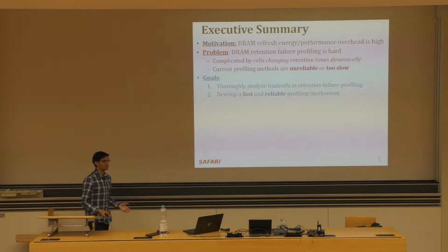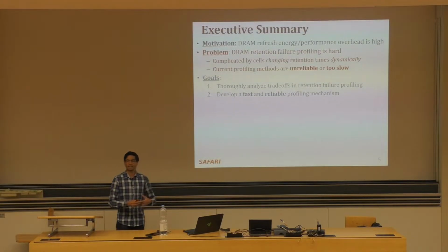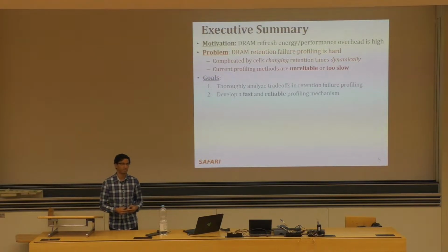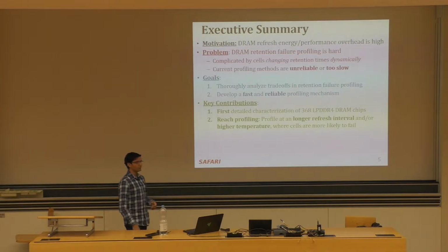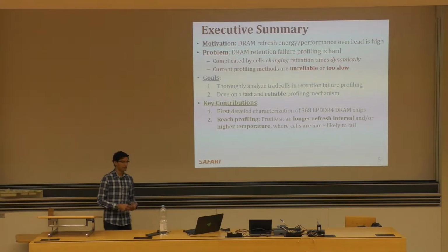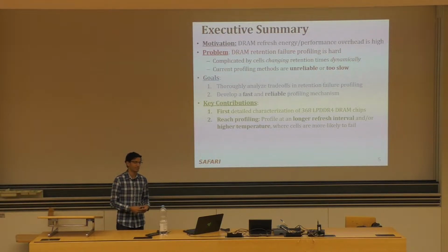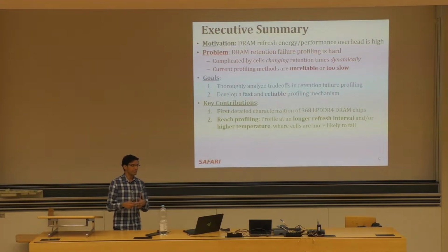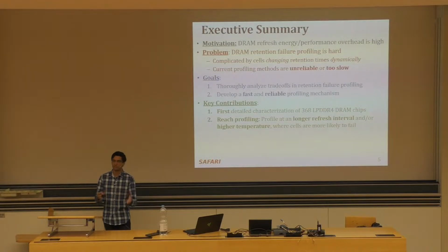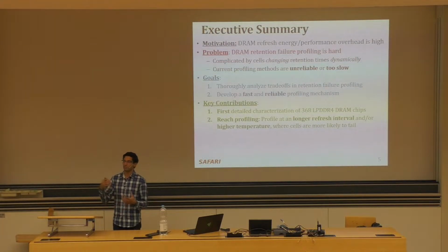And therefore, our goals in this work are twofold. First, we want to thoroughly analyze the trade-offs surrounding retention failure profiling. And second, we want to use what we learned to develop a fast and reliable profiling mechanism. And to this end, we make two key contributions in this work. First, we perform the first detailed characterization of LPDDR4 DRAM devices, and we use what we learned from that study to propose reach profiling, whose key idea is to profile at either a longer refresh interval or at a higher temperature than the target operating conditions. And this is because that's where cells are more likely to fail.